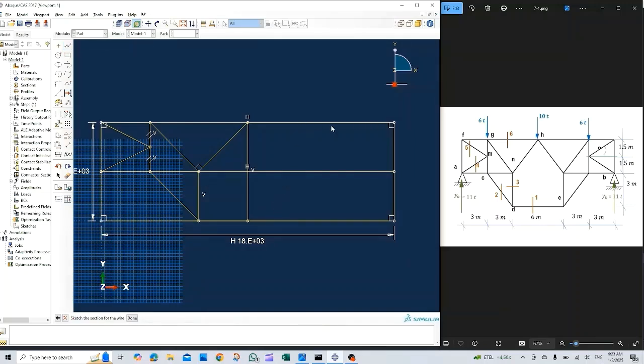Now we need to remove the outline of this shape, which is the previously drawn rectangle. Let's go here to the delete option, click it and choose the lines to be deleted.